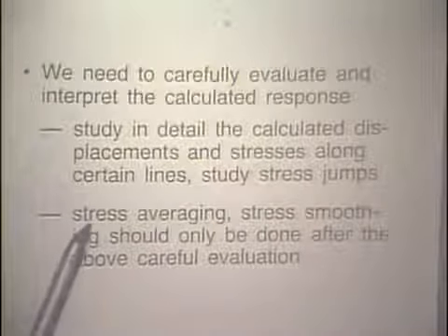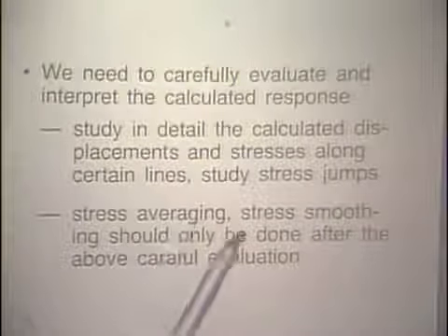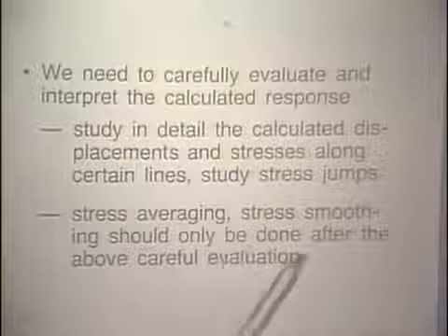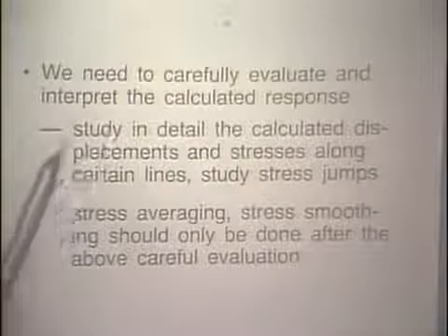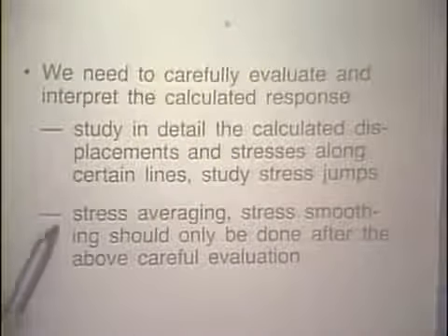And here I'd like to add that stress averaging, stress smoothing should only be done after the above careful evaluation. That's something important to keep in mind. I believe that you should first look at the stresses the way they have been calculated by the program, and then start thinking about stress smoothing, only after you have gone through this phase.